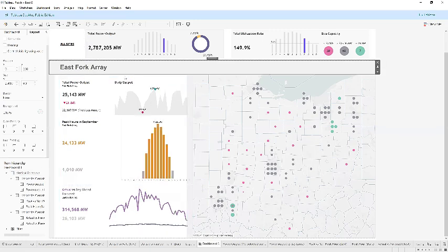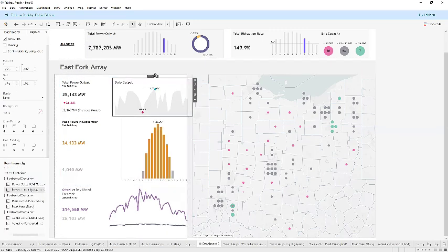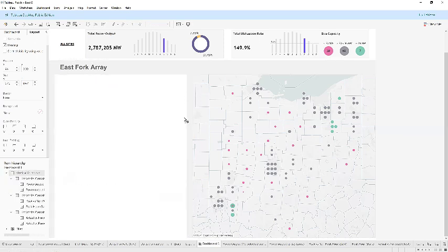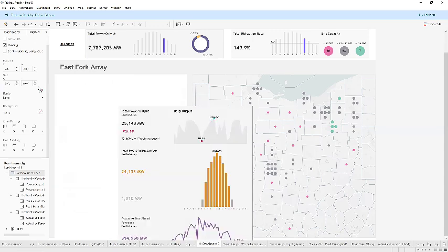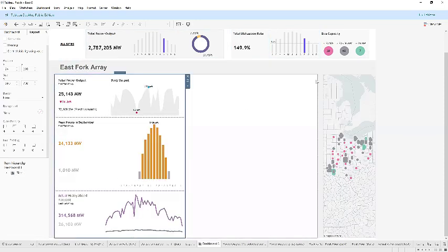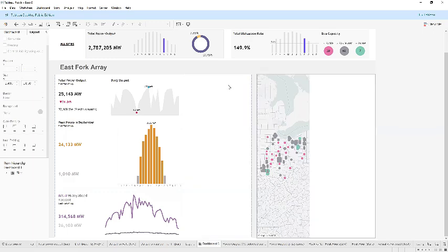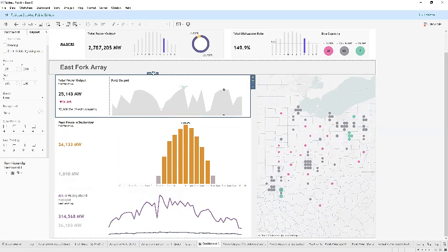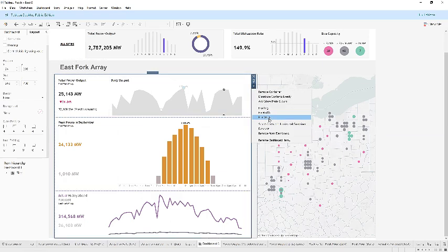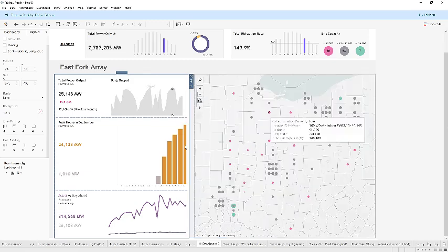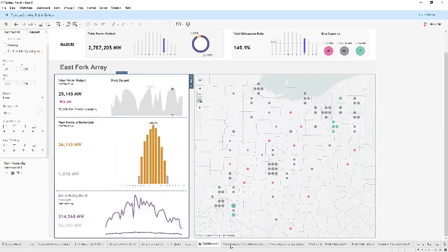Okay. So now let's put this in. We're going to have to put this in anyways. I don't know why I was doing that first. So let's put this in. I'm holding shift to put it in. So I want to put it here and leave, yes. Let's get rid of this blank that was just holding the space earlier. Now we can adjust the width how we want. Edit width and make it 575. Good.